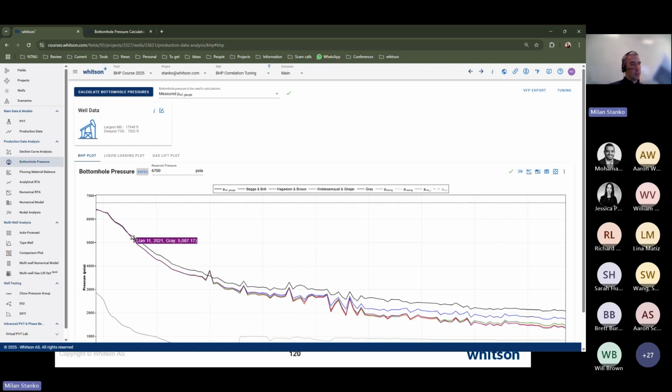Okay, but the main point here is just be careful with your water. Be careful what kind of water you're using. And if your water has a significantly high content of salt, something that changes the density significantly, make sure to use the proper number. And if you have data, in this case we are lucky we have some single phase data, then that helps you to find out if maybe your water properties are not set correctly.